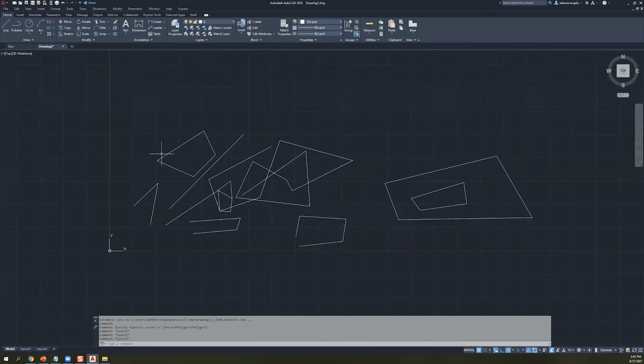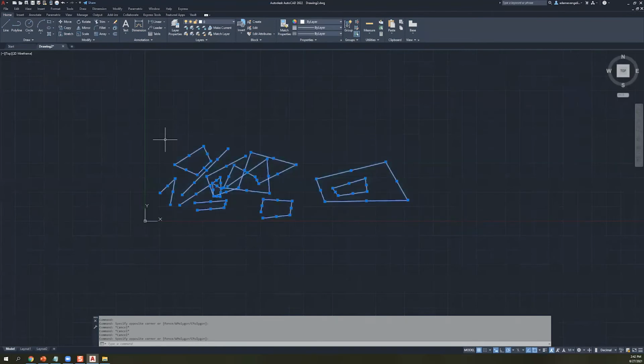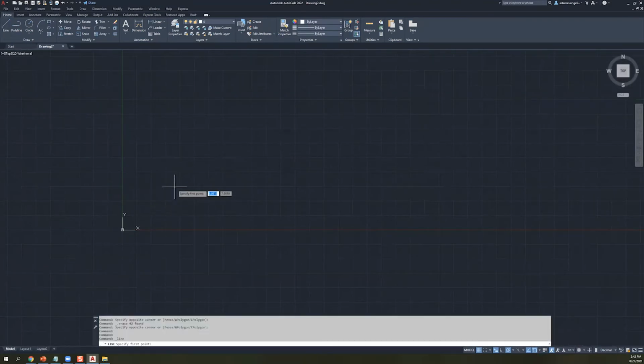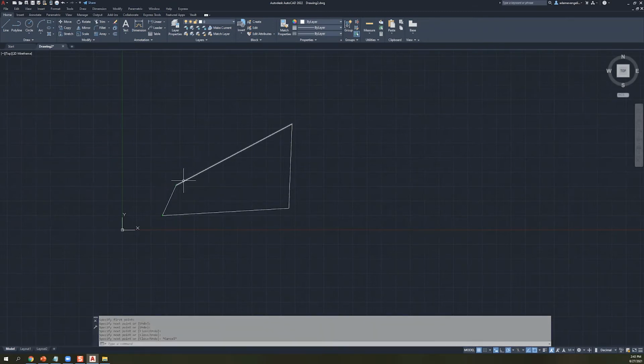This on screen, a bunch of scribbles that are loosely connected, and they look pretty good here so far, but we could do better, right? I mean, we need to do better, especially if we're getting paid for this type of work, right? So first off, I kind of mentioned this idea about closing and having coincident endpoints on these profiles, right? By default, object snaps allow you to do this pretty well, right? Just like that. And this is a decent square, right? This is going to do its job. It's going to be a closed region.